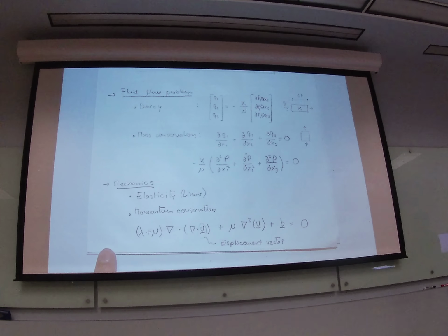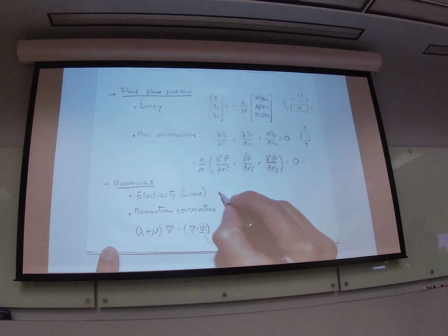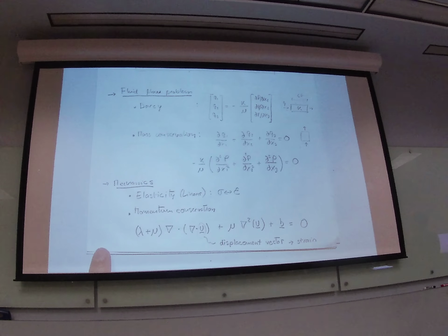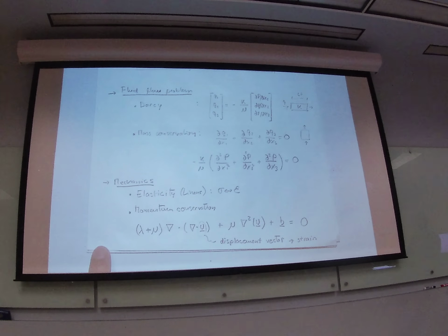If you remember, we obtained strains from displacements. Strains were a function of displacement, so as soon as you obtain displacements, then you also get strain. And since we know the relationship between stress and strain, which is given by this equation, we also get to know stresses.